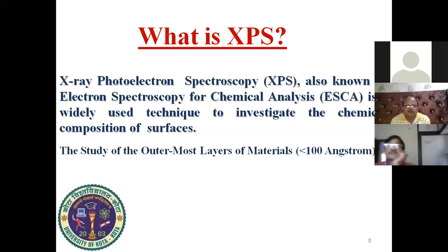This technique is surface sensitive, and hence cleaning of the sample is quite necessary before starting the XPS measurement. The surface of the sample can certainly be contaminated by our touch. It can be oxidized also. Water vapors may be present on the surface, and so many other contaminants can be present. But it can only provide surface information, from less than 100 angstroms thickness of the material.